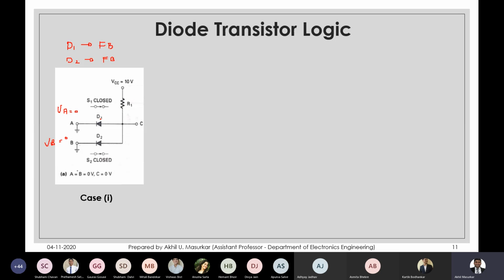Okay, so as you now move ahead in the technical courses, we need to slightly improve on the definitions of our devices. Initially, I know that it is taught to you that way only, that it is positive and negative, so diode will be forward or reverse. But it is not positive and negative, it is the difference. If the difference is more than plus 0.7, then we say that the diode is forward biased. That is good.